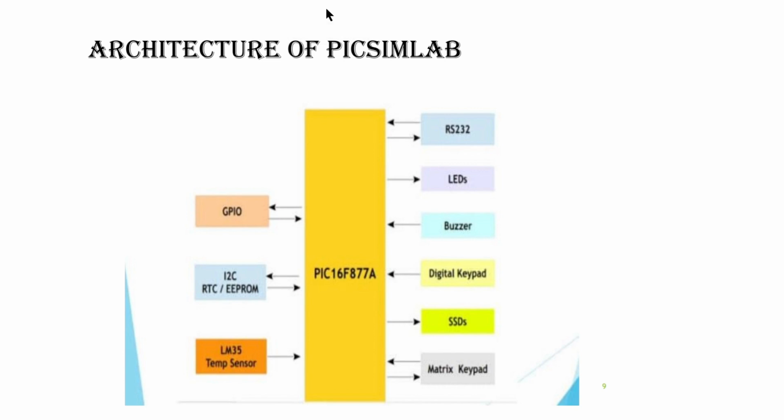GPIO pin. GPIO is a general purpose input output port which handles both incoming and outgoing digital signals. As an input port, it can be used for communicating on and off signals received from switches or digital readings received from sensors. As an output port, it can be used to drive outside operations based on CPU instructions and calculation results. For example, as an output port, an LED display based on calculation results or output drive signals to a motor. It supports I2C and can be used for test board features.